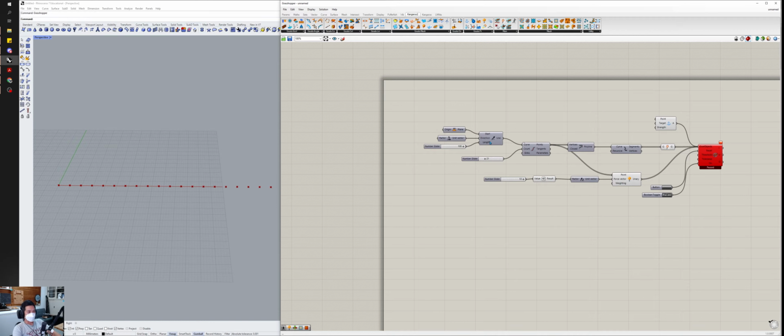So to do that, we're also going to extract 2 points from our original line. We could, of course, also take our points from here, right? But let's say if we just took our points from there, what would happen is that all the points would get locked in place, right? So we could either use line index from our set to pick the points that we want, or we could use, like in this example, the end points of this line, and let those serve as the anchor points.